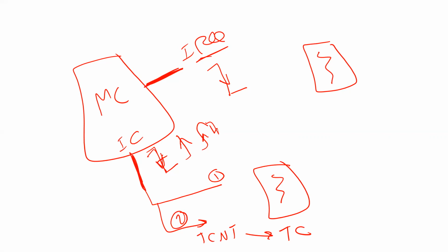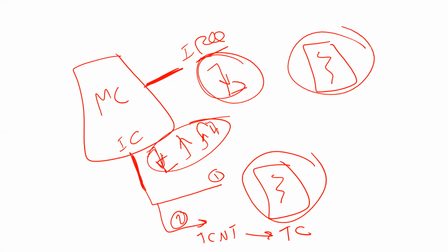This is the time of this event, or the count of this event. If you look at IRQ and you look at input capture, they're the same. Every time there is an event, an interrupt is executed. So I can say input capture can do the same job or the same task as IRQ, right? But input capture is going to do one more thing, which is this one.